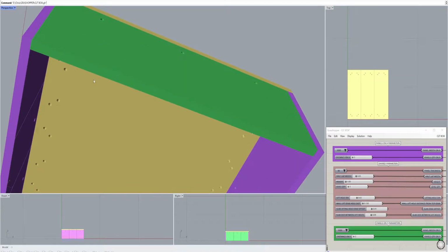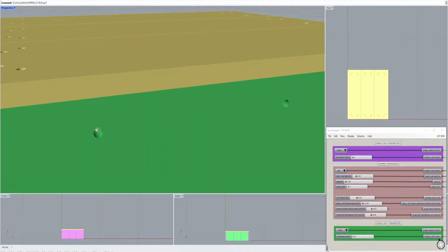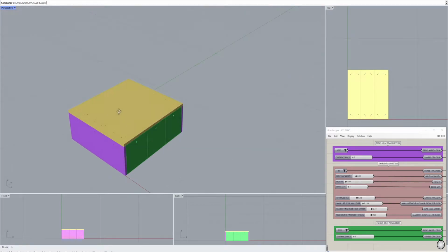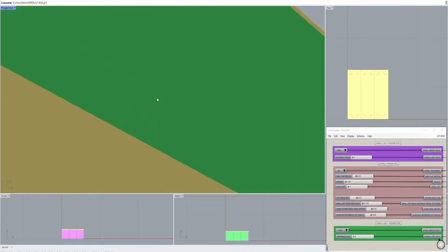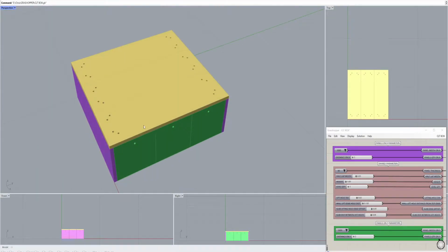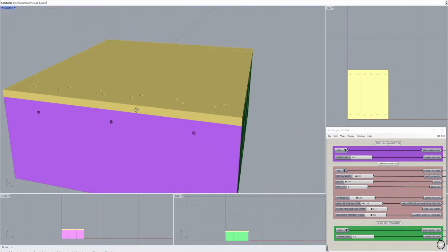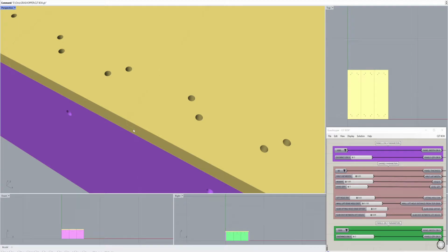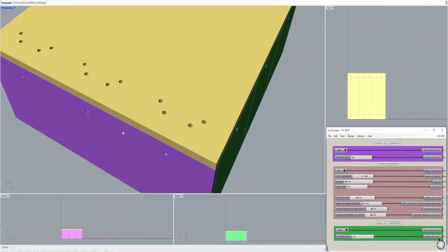Basically, that means that this is one component and includes the half lap already and the lifting hole. So we just create this square or rectangle based off of component pieces, and they are machine ready. Well, kind of. Actually, you would have tolerances in here, but for now, it's pretty good. So we had 4 walls, and I was planning on putting on the slab, which of course you can see is done here, and it also includes the half lap, controlled by the same half lap width over here. So as you can see there, it's adapting.